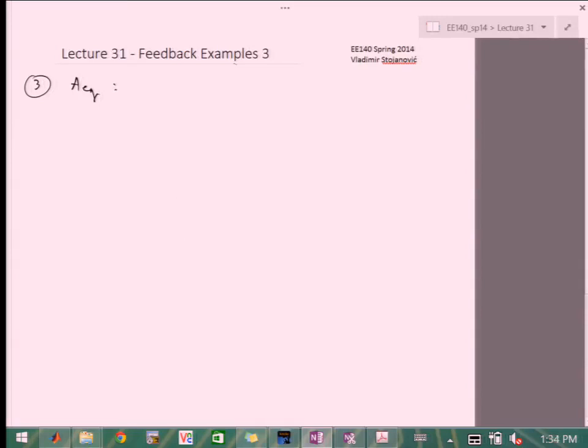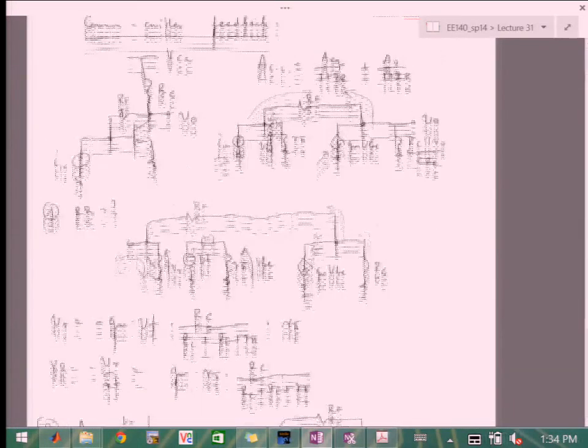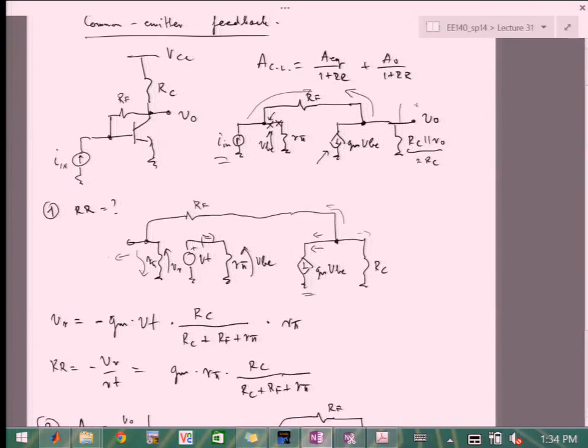Okay, for that, again, we apply the trick. We need to null the output, see what the input termination network looks like, have our gain, and then null the input and see what the output loading network is. So we have I in, and then if we go back to the previous drawing, over here, if we null the output, what we see from the input is just RF, because we've nulled this node over here.